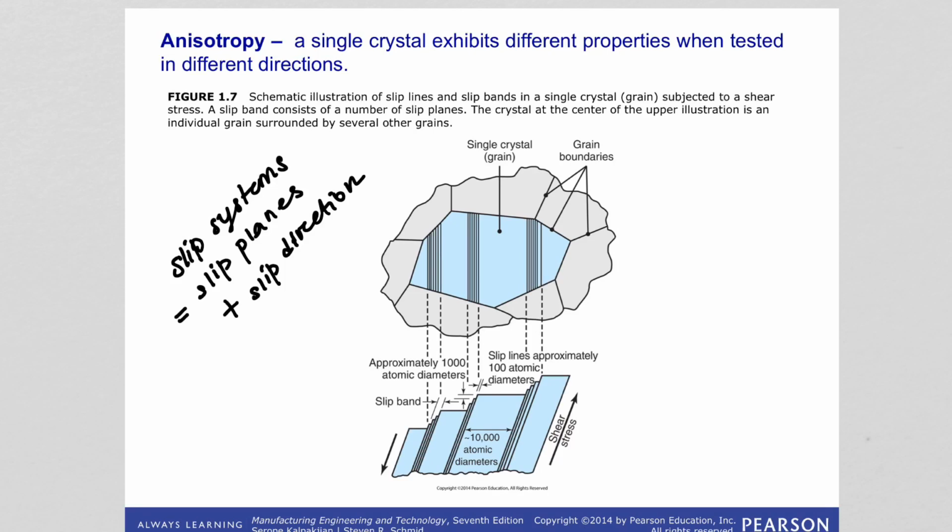So the slip or the deformation will happen at certain planes, in a certain direction. And those directions and planes are usually the most densely packed atomic planes or directions. This is because the slip first starts there, since these directions or planes require the least amount of stress to start the slip. That's why once you reach that critical stress on those planes and directions, the slip happens.